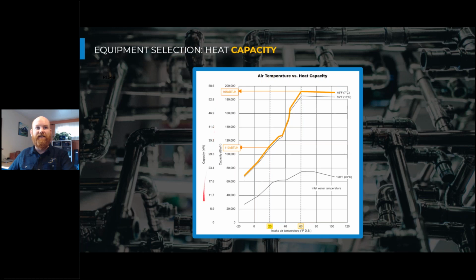This is for a CO2 heat pump water heater. So you can see we're generating heat down here low on the ambient air scale. But if this was for an R134A heat pump water heater, we wouldn't be heating on the left-hand side here of 40 degrees Fahrenheit. So that wouldn't be heating water.